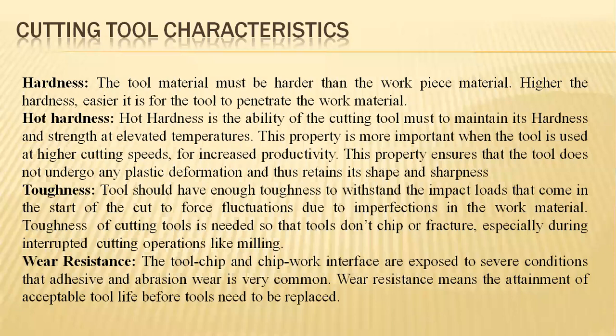Next point is the hot hardness. It is the ability of the cutting tool to maintain its hardness and strength at elevated temperatures, which are nominally used at high cutting speeds for rationalizing the productivity of the materials within the industry, and even a strict condition, that is, without going to plastic deformation, the entire process needs to be commenced to retain its original shape and sharpness.